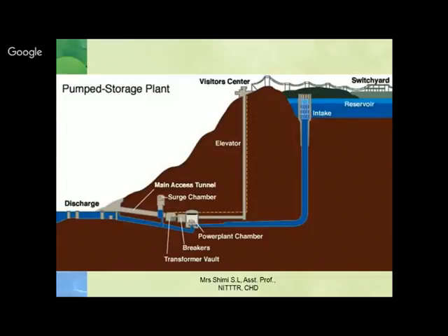But in this form, like from the hydro, you cannot store the energy and keep it. So this is a storage plant. This is not a generating plant. Actually, it's a storage plant. During the non-peak hours, we pump the water up and keep it in the reservoir, and when it is the peak hours, when the cost of electricity is higher, at that time we generate.